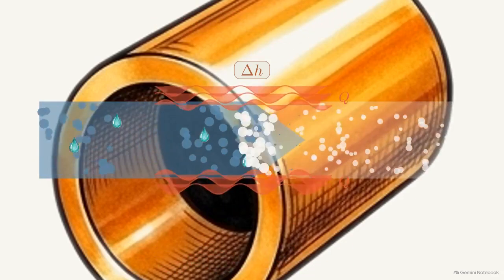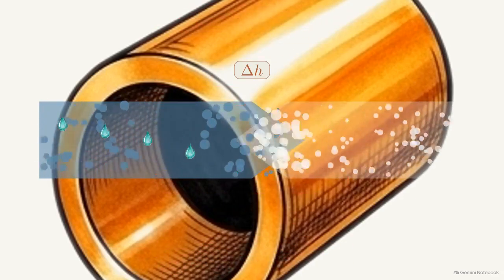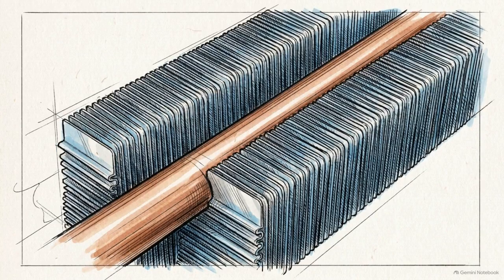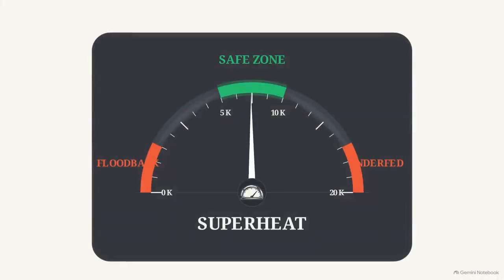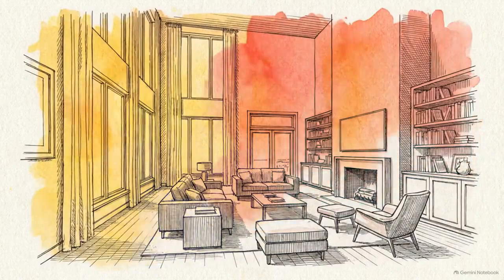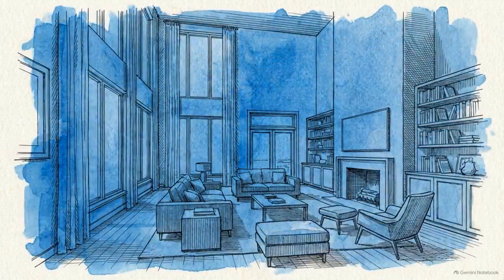Successful HVAC execution relies on flawlessly balancing the fluid mechanics of the refrigerant against absolute thermodynamic equations. System designers must continually maximize the surface area and heat transfer coefficient for optimal heat absorption, while strictly managing the refrigerant flow to maintain safe superheat levels. The evaporator is the component where the cycle meets its primary objective. It is the interface regulating the temperature of a physical space.